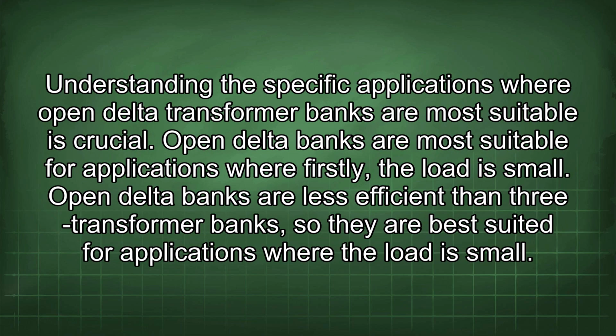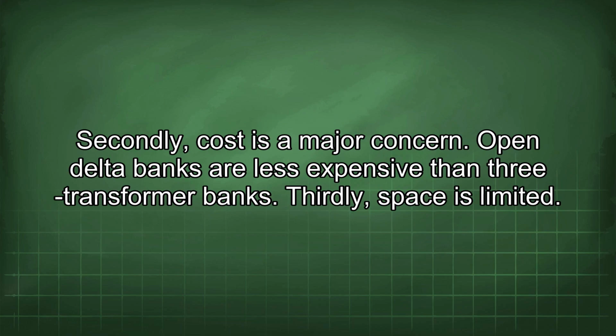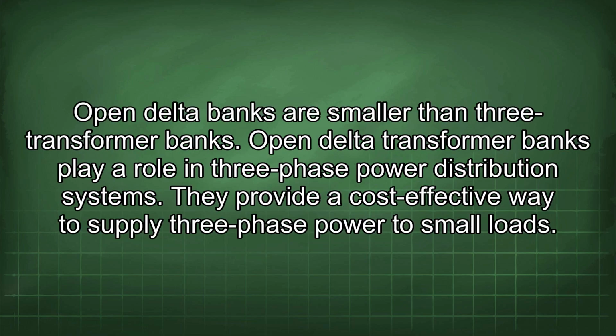Understanding the specific applications where open delta transformer banks are most suitable is crucial. Open delta banks are most suitable for applications where, firstly, the load is small. Open delta banks are less efficient than three transformer banks, so they are best suited for applications where the load is small. Secondly, cost is a major concern. Open delta banks are less expensive than three transformer banks. Thirdly, space is limited. Open delta banks are smaller than three transformer banks.